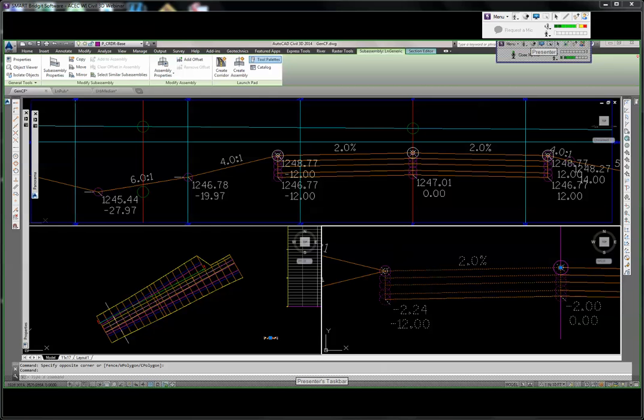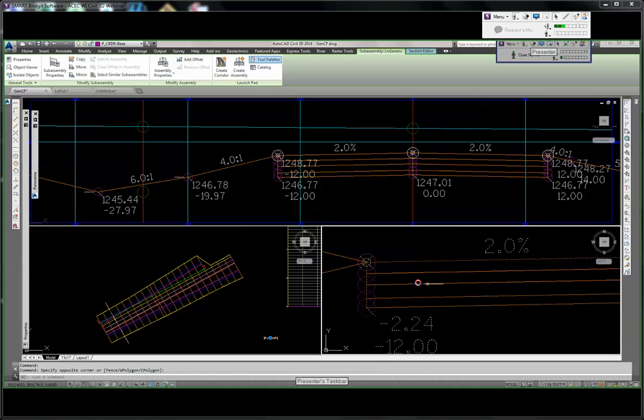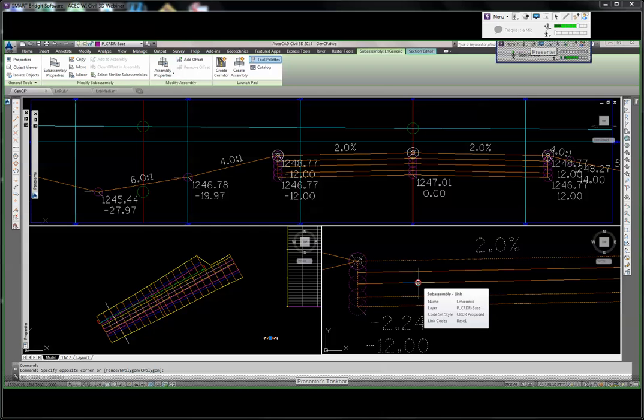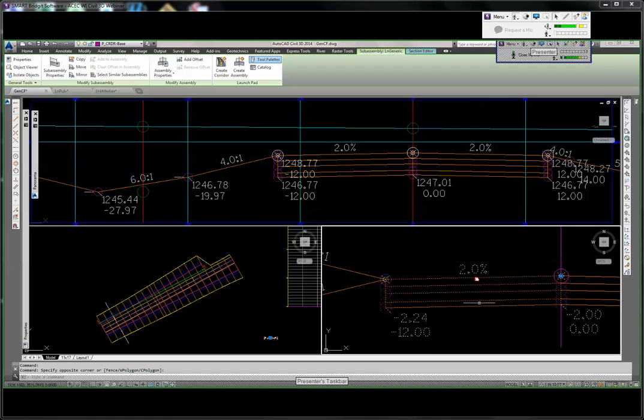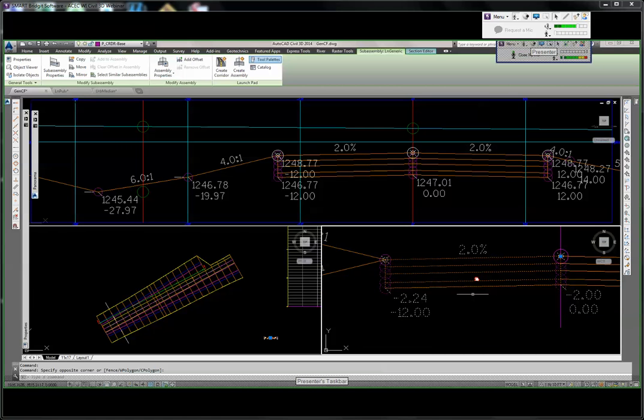And finally, I want to talk a little bit last about the pavement here, the measurements here. Autodesk subassemblies are measured as just different material depths. I need 4 inches of this, 4 inches of this, 6 inches of this, and so forth. This subassembly is actually measured from the top going down. And really, as long as you get to the same depth, that's fine, as long as you know what you're getting. And actually, I'm doing this particular topic so I can show you an error that crops up if you get into a certain situation.